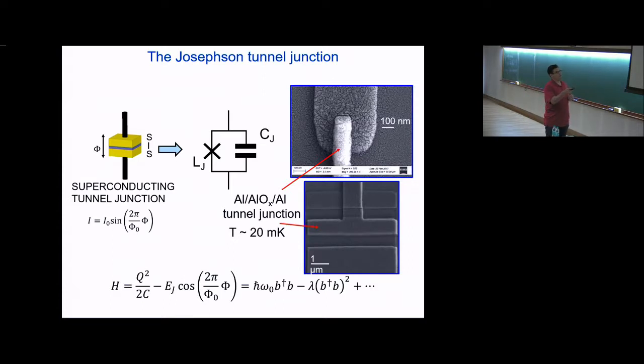This is a qubit junction here. You see it's very small. Here's the lower layer. Here's the upper layer resting across it. And in between is a nanometer or so of aluminum oxide. These are almost always made out of aluminum these days. And then here you see the really big difference in size scale. This is an amplifier junction. It's several square microns, several microamps of critical current. This guy here is a few hundred square nanometers.